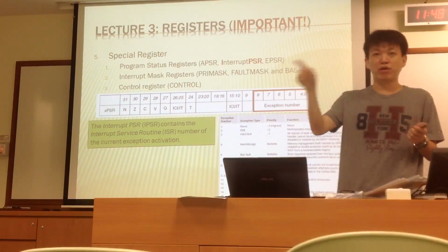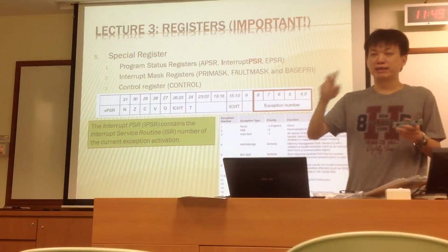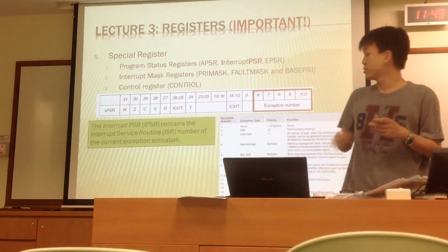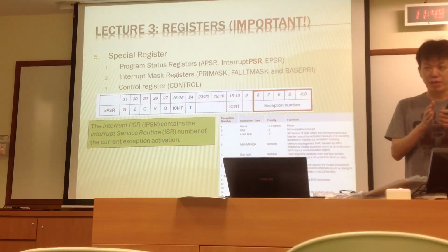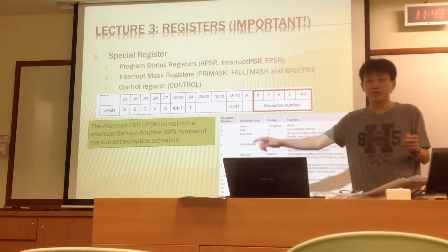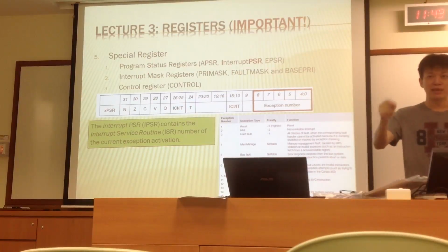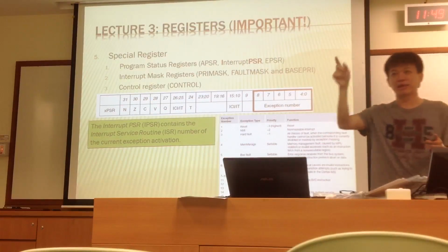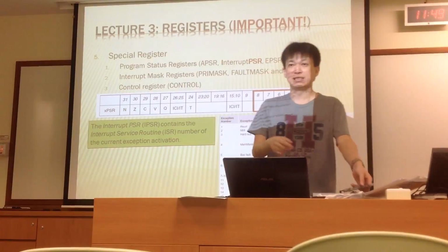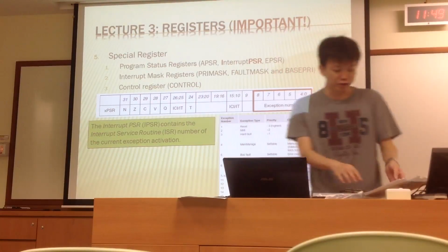The rest: there's one that uses a for loop to create the delay. There's another one that uses the SysTick interrupt. You turn on your LED, but every 1 millisecond it goes to the SysTick interrupt to update the tick. There's an ms tick, every 1 millisecond it ticks. Every time the tick passes 1000, it switches the LED off or on accordingly. So the SysTick idea is very useful.